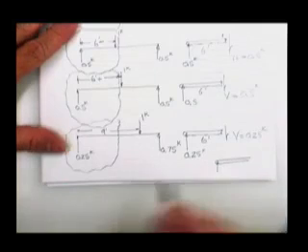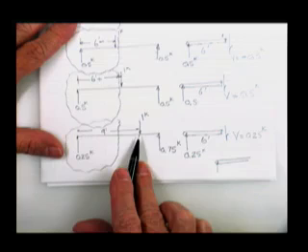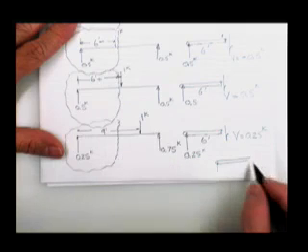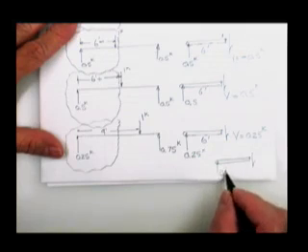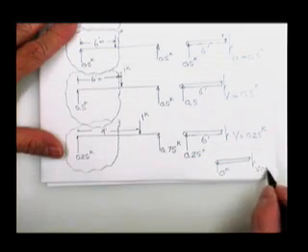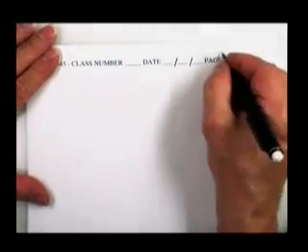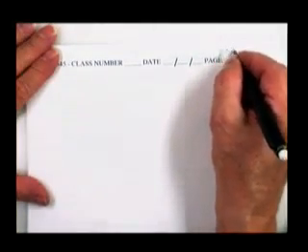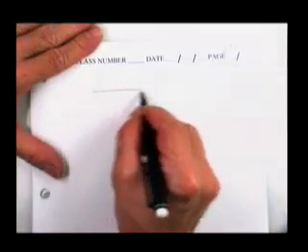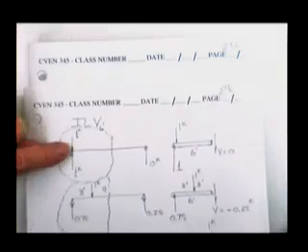When the load is moved to the 12-foot mark, this shear will be 0. Now I'm ready to plot it. Here's the beam. When the load is on the left end, the shear is 0.